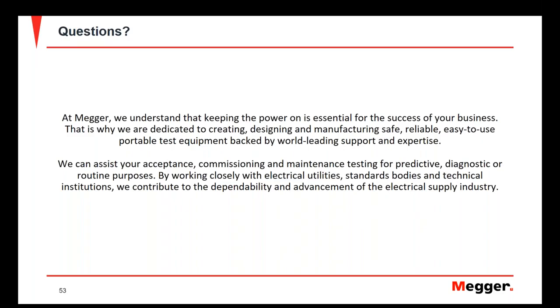The OCR 15D or 50D is a test set which has a high amount of voltage, which is capable of injecting whatever amperage is required through the recloser, and also capable of handling the changes in impedance of the recloser while the test is conducted, because the output voltage is high. Because of that requirement for a higher test voltage, we need a special instrument to be able to test oil reclosers.